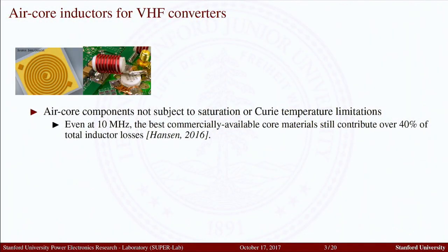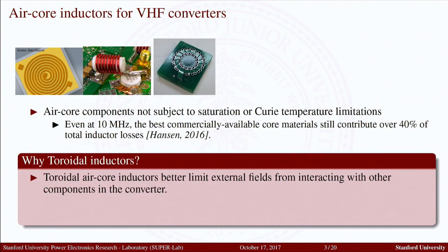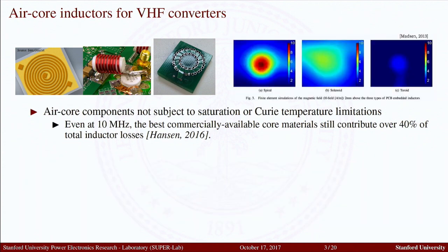gives you the opportunity to fabricate inductors by simply printing traces on a board, or using just a little piece of coil around a plastic core, or just printing them on a printed circuit board and avoiding any fabrication techniques. And we take advantage of the geometry to reduce the electromagnetic fields that are accidentally emitted when we design these power supplies. Our roadmap is also to make converters cheaper to fabricate.